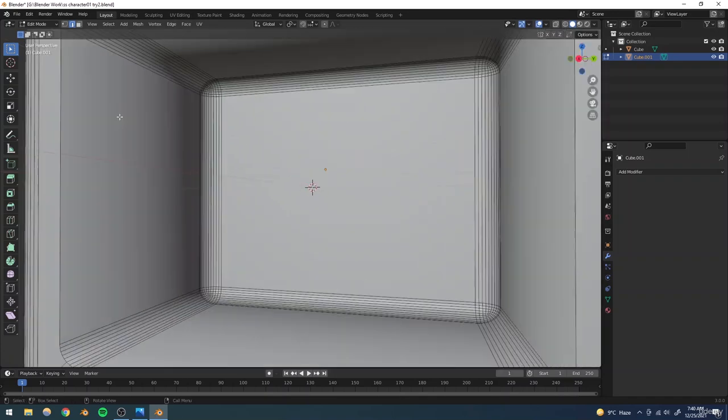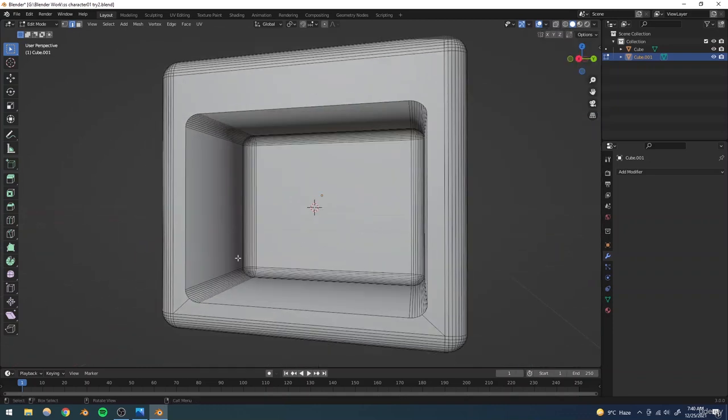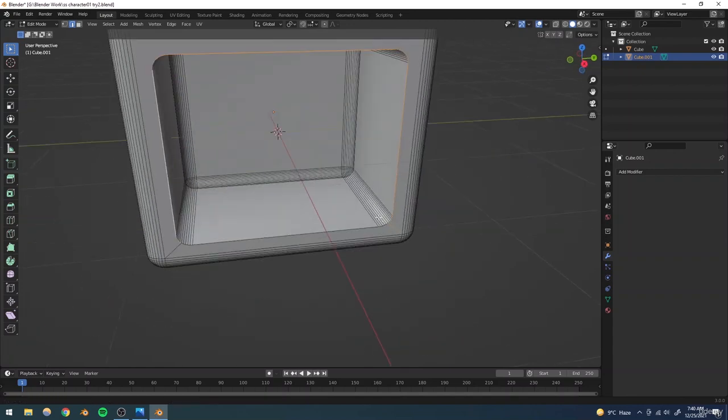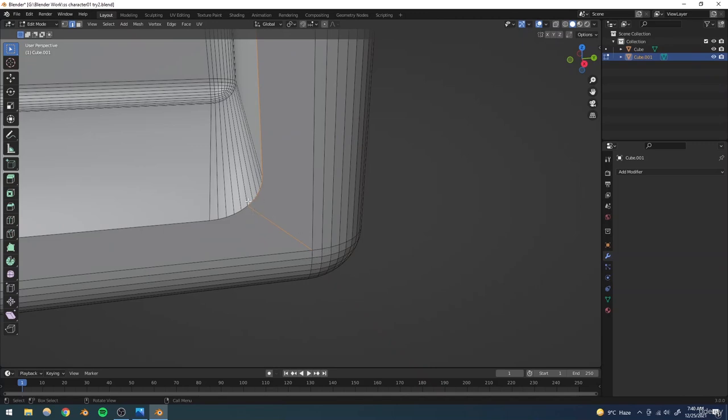Okay, now either we could select this edge and press Shift and select these individual edges, but that's going to be very, very time consuming, and it's going to be very inefficient as well. So I'm just going to press Alt and just select it, and I'm going to see that these bottom edges are not selected for some reason, because this edge loop has basically been diverted off to this side.